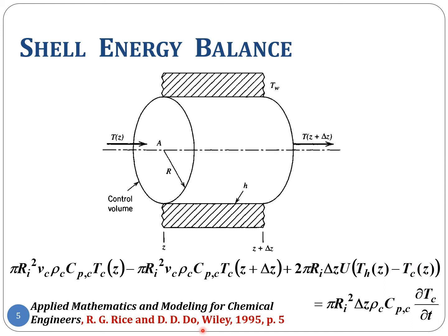And when you take the derivative with respect to time, the reference temperature will also get cancelled, and therefore that is not considered, right? So the first two terms indicate the energy convected by the flowing fluid at the inlet and the exit. The difference is what should be the energy added by the hot fluid and the accumulation.